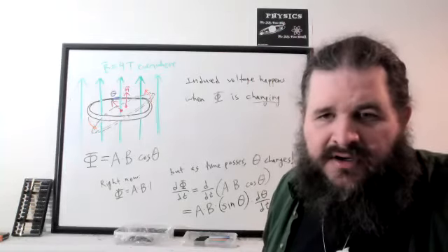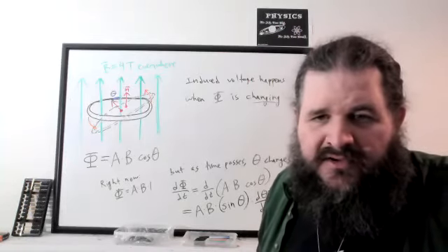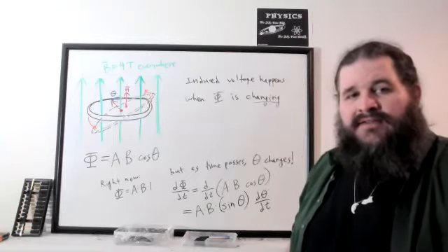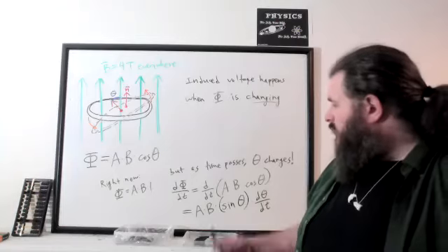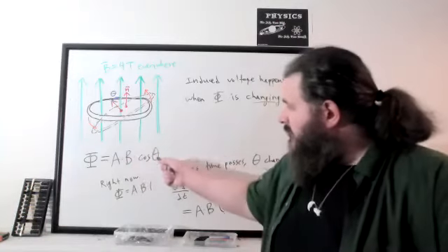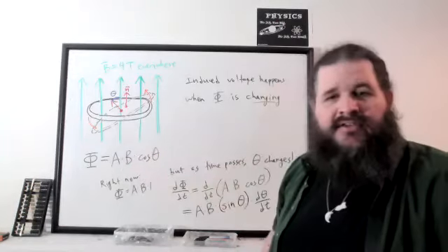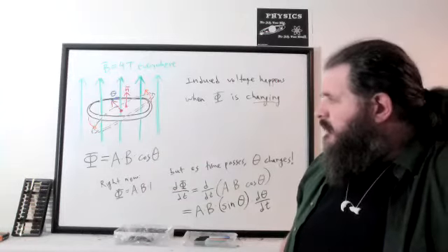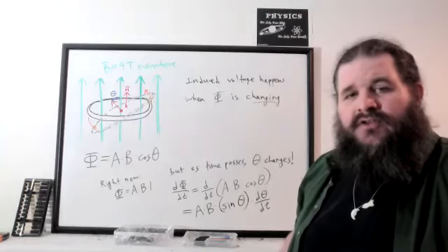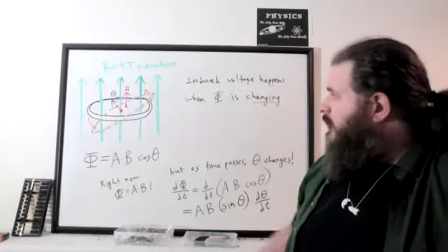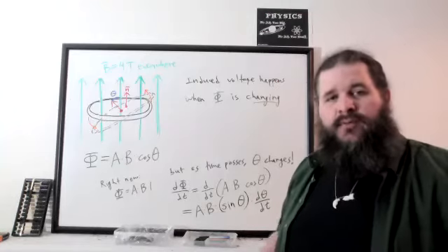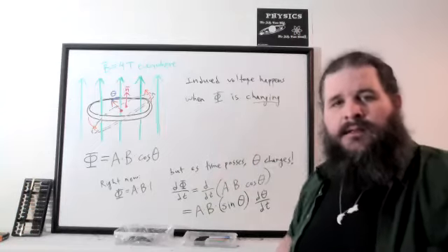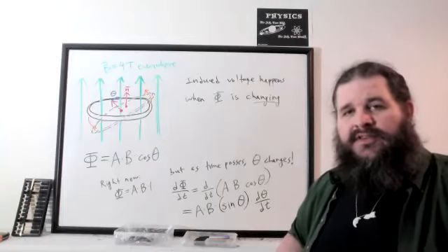To maximize energy in a generator, would you have a loop that both increases and decreases in area? You could certainly combine these effects. You could have a situation where the area is changing and the angle is changing and the magnetic field is also changing. So you could have all three of these changing. But in a typical situation, we'd be focusing on just one of those changing and hold the other ones constant. Like in this case, we're assuming the loop of wire is rigid. It's not going to stretch and compress. All it's doing is rotating. But it's certainly possible to have more than one of these changing.